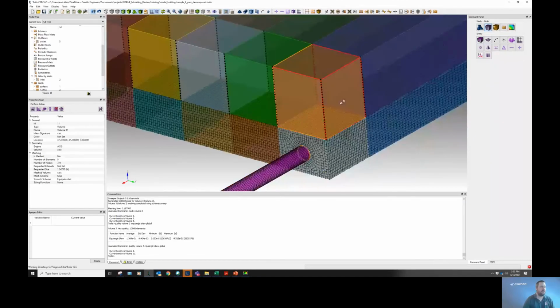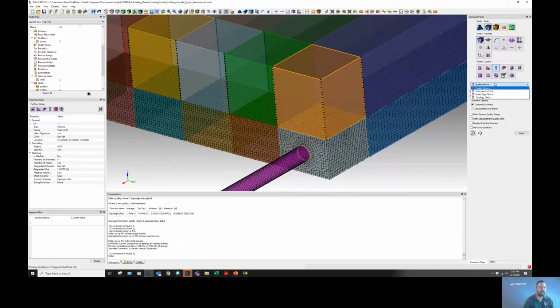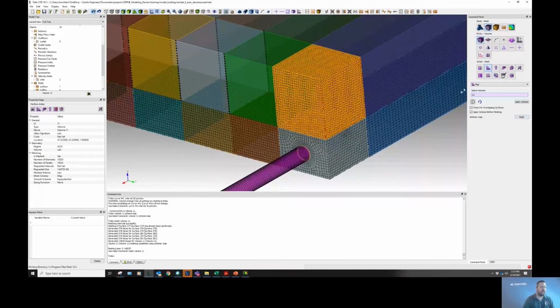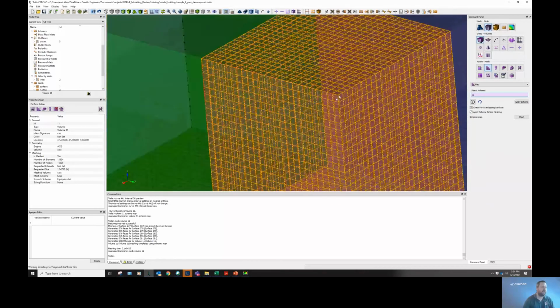The other volumes, we've defined the edges. Again, we've got 24 intervals or 3-inch size. This mesh is approximately 3-inch. And so we would come here and use a map feature to develop a uniform hexahedral mesh of 6-faced elements.